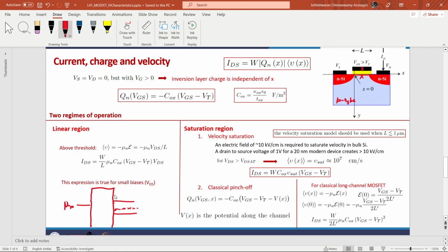No electrons are available. So under equilibrium considerations, what we will have is essentially the picture of band bending. My Fermi level will bend like this, and then my valence band will be close to that, and my conduction band will be above that. Now, by increasing the voltage, I can lower this to the point where inversion occurs.